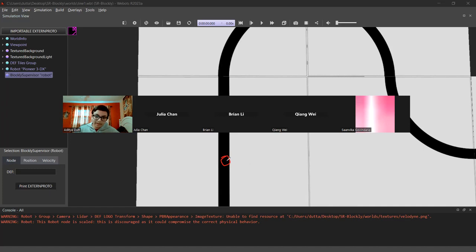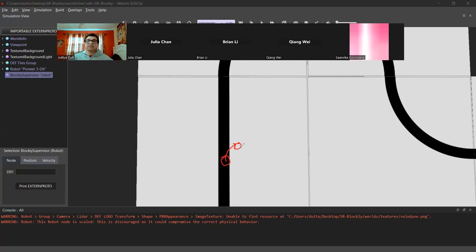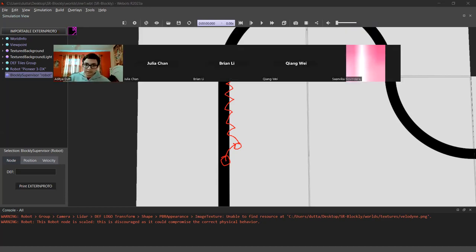What will end up happening is the robot will turn and move in this direction. Then the robot will see a white point here, at which point it will detect that it's on white and it's time to turn the other way. So the left motor will stop and the right motor will go forward, and it'll cause the robot to go this way. In this back and forth motion, the robot is able to trace the whole line. It looks kind of jittery, but this is about the best that's possible with just one-eye line tracing.